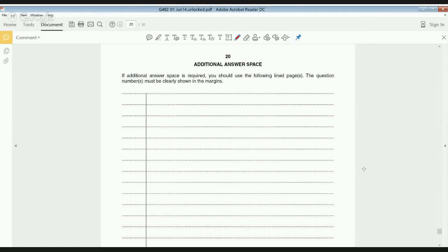Legend Footy says, what does 6 volt 1.5 watt filament lamp mean? So 6 volt, 1.5 watt. That's telling you the power rating and the voltage of the lamp. All that means is that if you connect the lamp to a 6 volt supply, it will produce 1.5 watts of power. From that information, so that's our power and that's our voltage, you could then find current, resistance, whatever you want, using the 3 power equations: P equals IV,